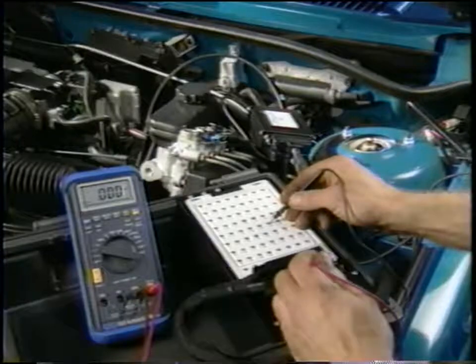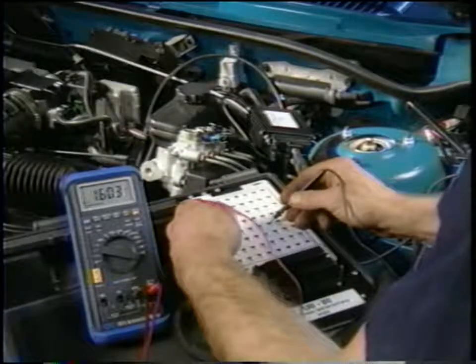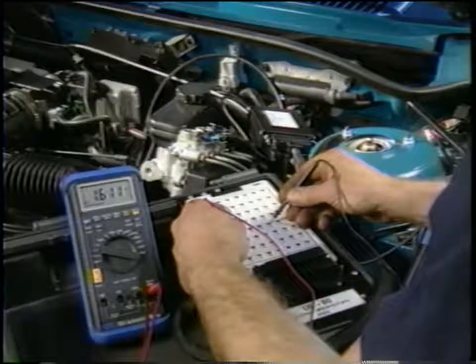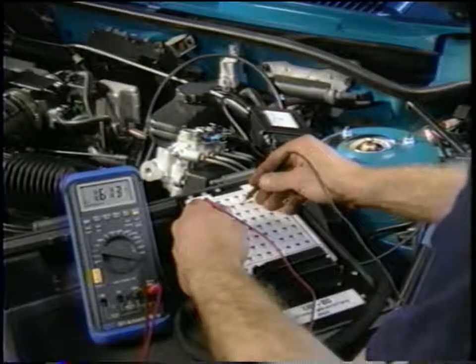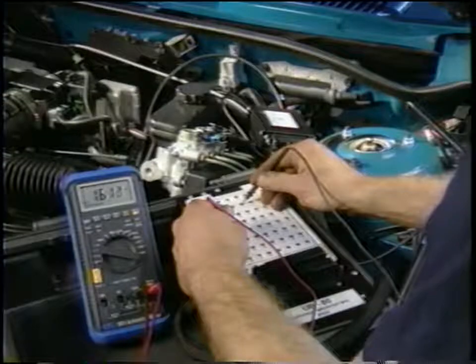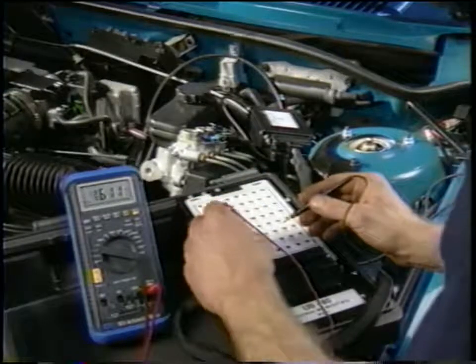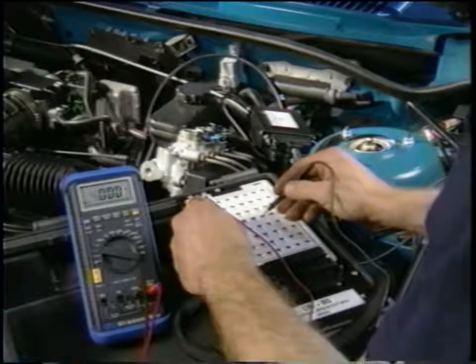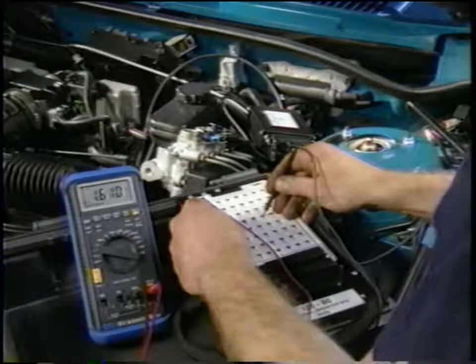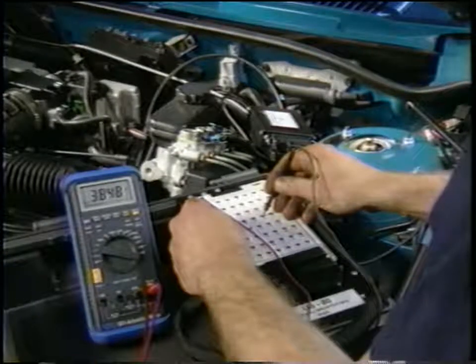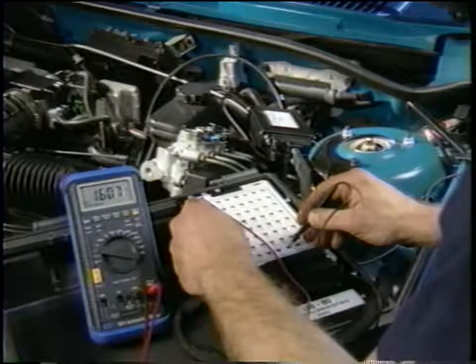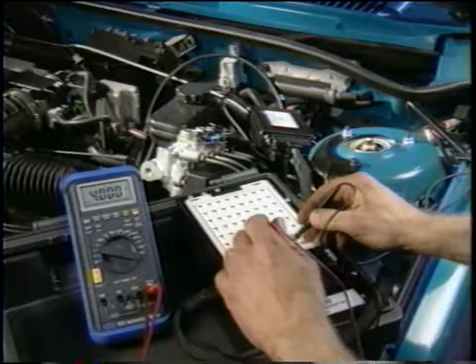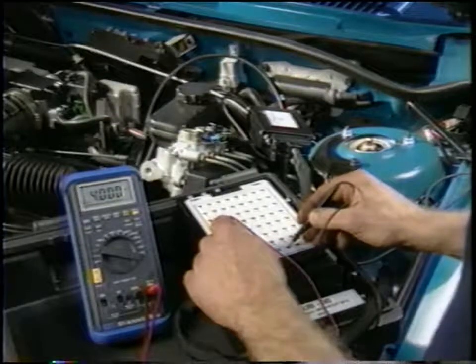Wheel speed sensor problems are a common ABS fault where a digital volt-ohm meter and breakout box come in handy. When a fault code for a wheel speed sensor is present, the typical shop manual diagnostic procedure usually involves a resistance check at the control module using a breakout box. This will tell you whether or not there's continuity in the circuit and whether or not the resistance at the wheel speed sensor is within specification.